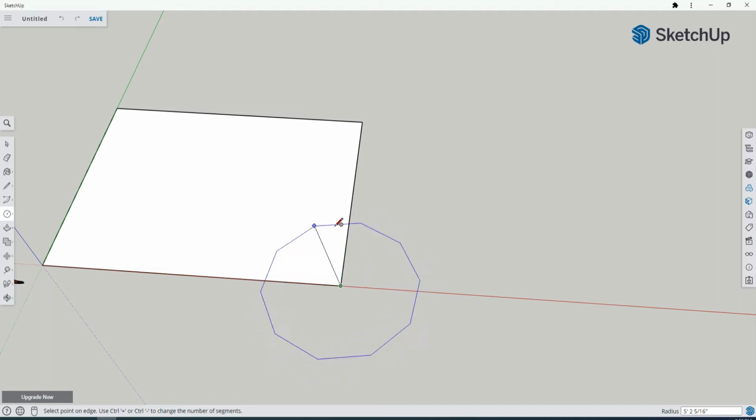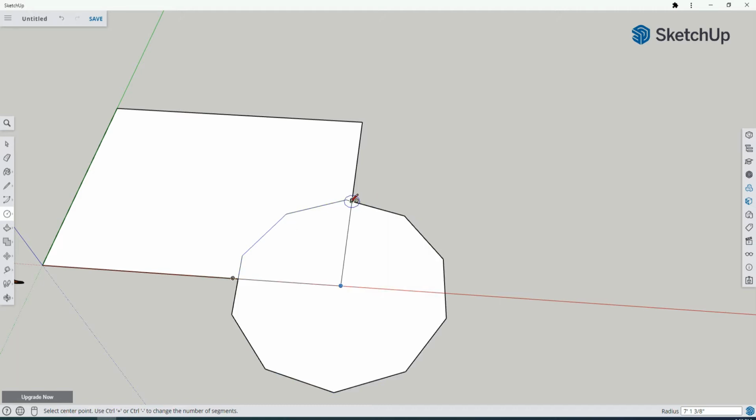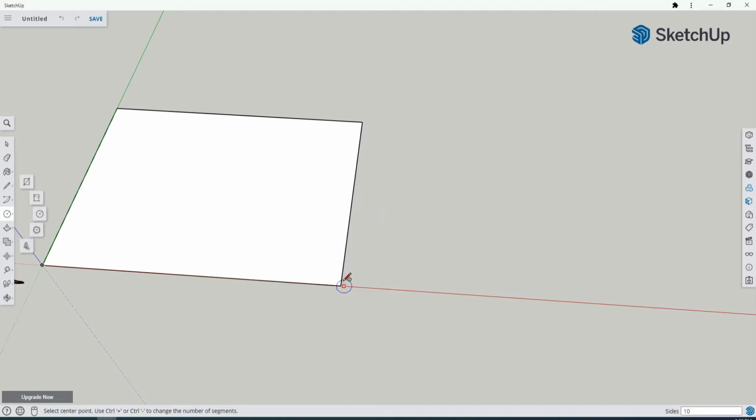Using circles in CAD programs like SketchUp is mostly about balancing this trade-off. More sides makes the program run slower, less sides starts to look less like a circle. So honestly, I just use the default normally, which is 24 sides, and that works for almost everything except for a spiral staircase like I showed.